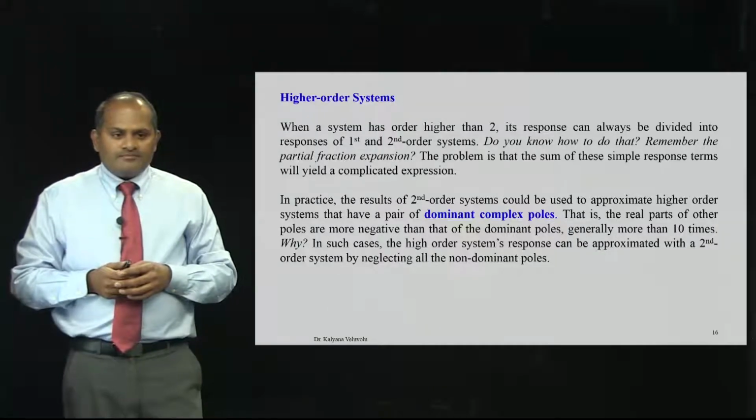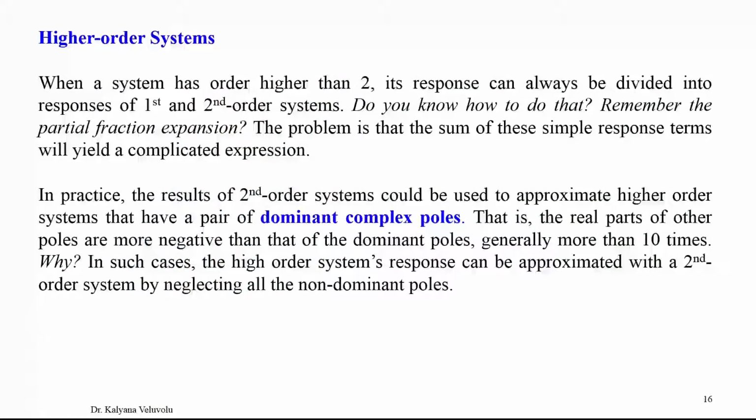When you refer to any higher order system, its response can be divided into responses of first and second order systems. If you have a second order differential equation, I can break it down into two first order systems and calculate the output of the two first order systems individually.